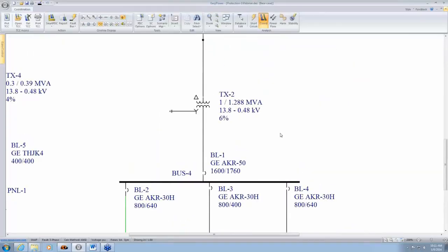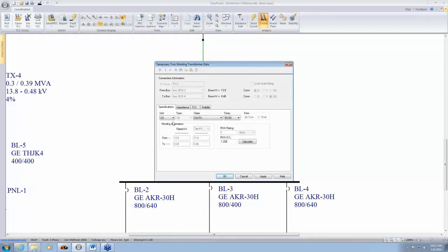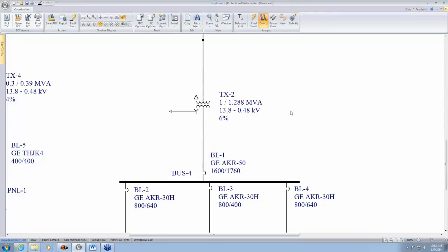The ANSI C57 standard provides several damage curves for transformers, and we model all of those. If you look at the dialog for this, you'll see that there are different types. Right now this is of oil type. As per the ANSI C57 standard, for dry type there are 2 categories, and for oil type there are 4 categories of transformers, and these categories are primarily based on the kV rating of the transformers. And so you can plot the damage curves for these transformers.